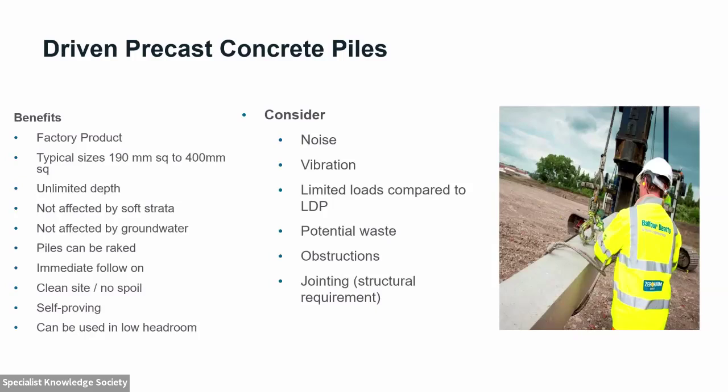Some points to consider around precast piling: clearly, it makes some noise if you're driving a pile into the ground, and it creates some vibration. So that might have an impact around the location you could use a precast pile in. I've covered the limited loads and a potential waste. If the piles don't drive, you drive them to a set and you get piles sticking out of the ground, you have to crop them off, and then you've got effectively waste concrete, which you can't do anything with.